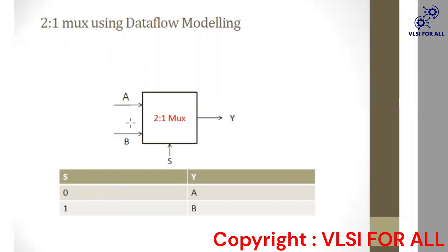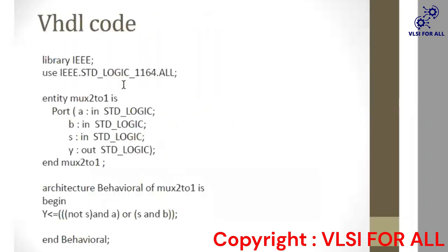Moving further. As always, we first declare the IEEE libraries: library IEEE, and use IEEE.std_logic_1164.all. After that, we will create an entity.